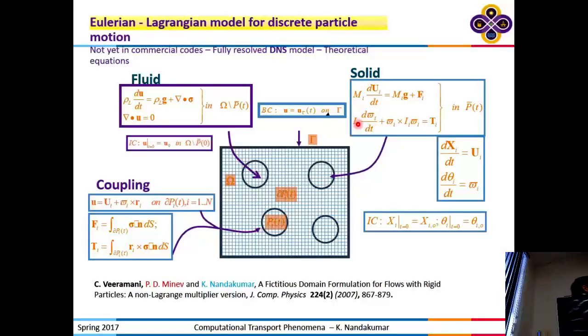So to gain any advance in this area, you shouldn't have to remesh. With the current technologies in COMSOL, for example, if the particle moves, the geometry changes. I need to remesh because I'm solving only for the flow domain. So if I give you an array of spheres that are fixed, like in a packed bed, you can then mesh the interstitial spaces, like in porous media, and then you can solve through direct numerical simulation. Okay? But if the particles are moving, then you need to have the ability to remesh or develop new algorithms.